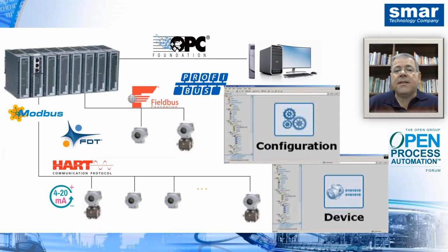In this didactic plant, we can work with various technologies. We can work with controllers, with Foundation Fieldbus. We can work with the existing HART technology. We can work with Profibus technology. And to communicate with the supervisory system, we can utilize OPC for this purpose through the Ethernet network.